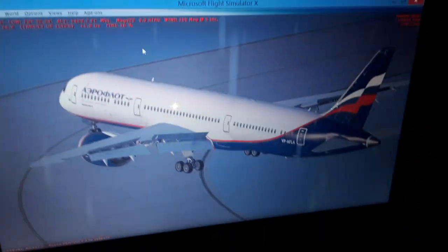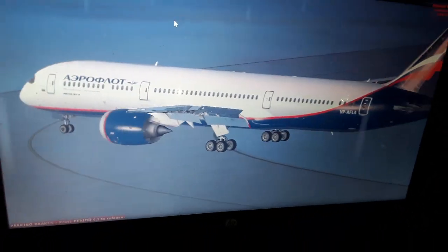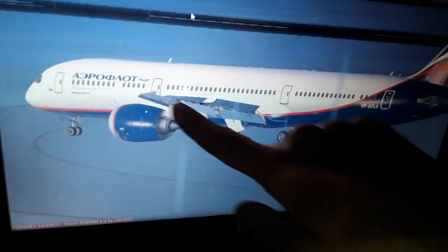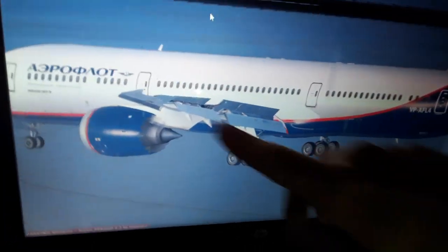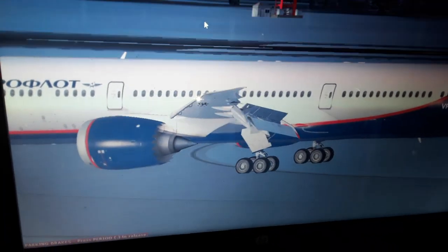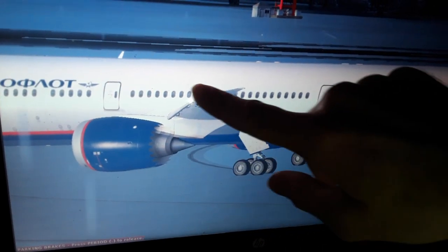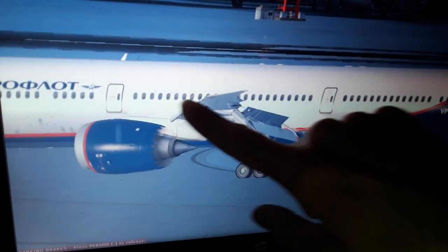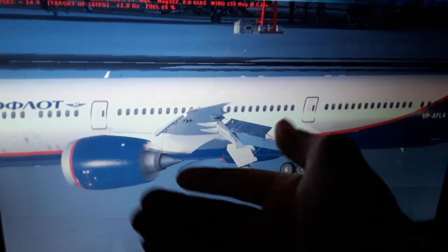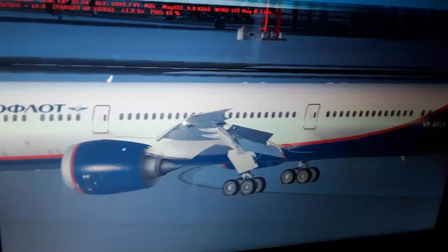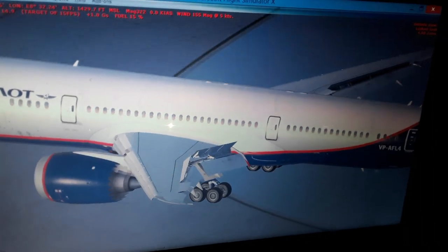So you see, also we have the bottom surface of the wings over here. As we fly it is more flat and we have the flaps extended. So we have, using the Bernoulli theory of fluid, as we accelerate for takeoff and then we fly, and also we have mainly a positive angle of attack. The airflow is moving slower below the wings, so we have higher pressure, which pressurizes the wings of the aircraft and the weight up into the air.